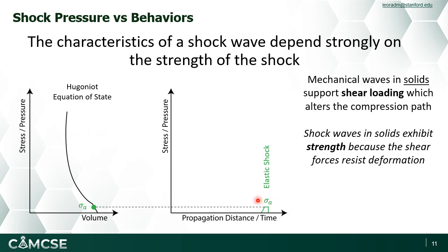So as we increase the pressure now, we end up seeing something that looks a little bit more like this for our shock shape, as we have the initial jump reaching something that is near the Hugoniot elastic limit. Then we see some sort of response following that, and a subsequent rise in pressure to reach our highest stable shock pressure that remains stable for a certain amount of time and then ultimately will release.